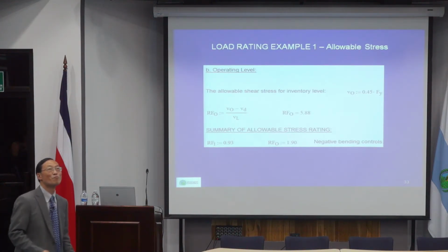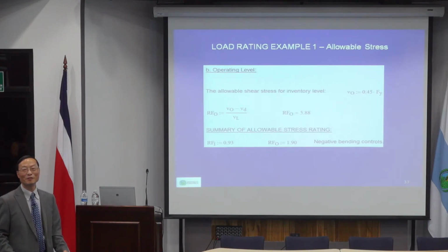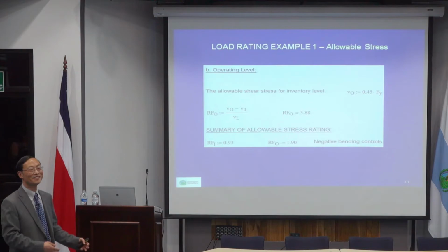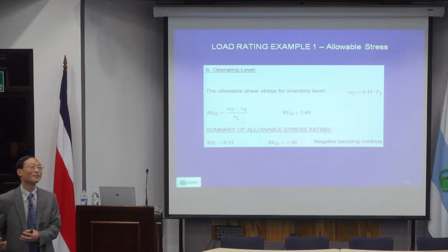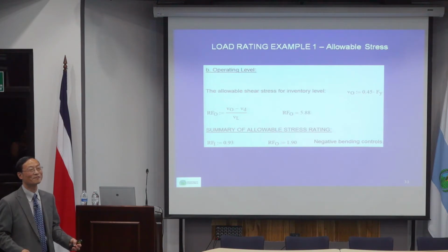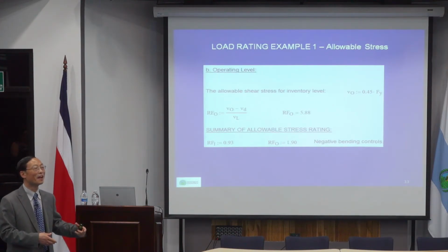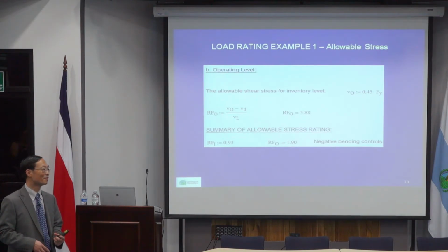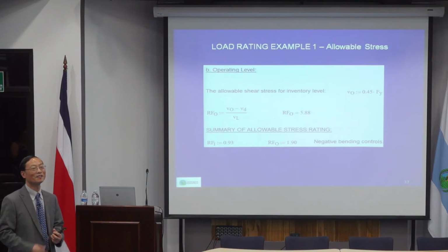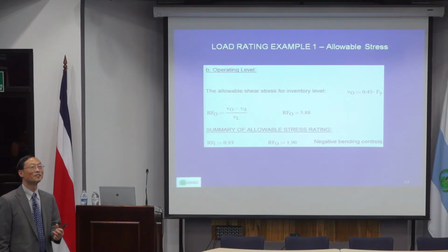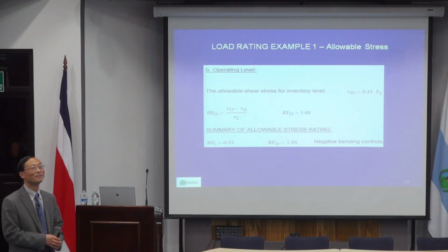That's why for anything, if you want to use software, you should ask yourself, can I do that manually? If you cannot do it manually, it's always questionable because you don't know what comes out of the software. Even if I use software, I always do some very quick manual calculations to see if it's in the accuracy range of that magnitude. Manual calculation is becoming less and less common, but for any structural design, it's probably always required to do a very quick hand calculation just to see whether the output makes sense.